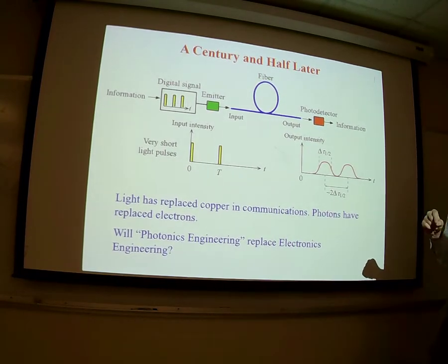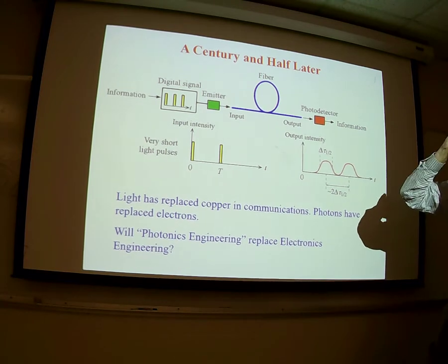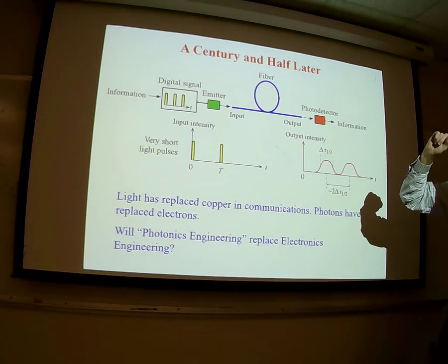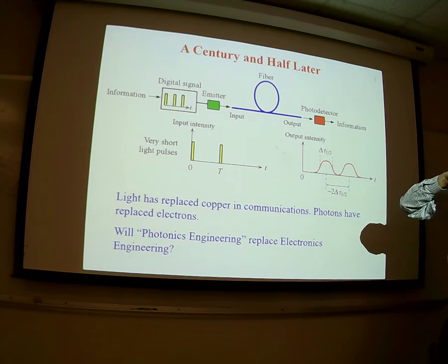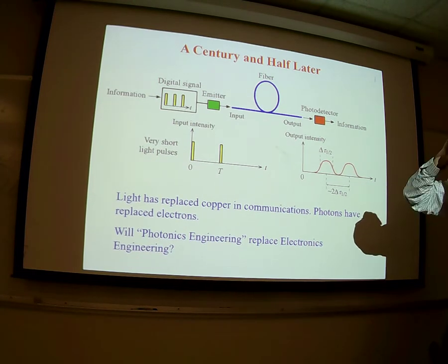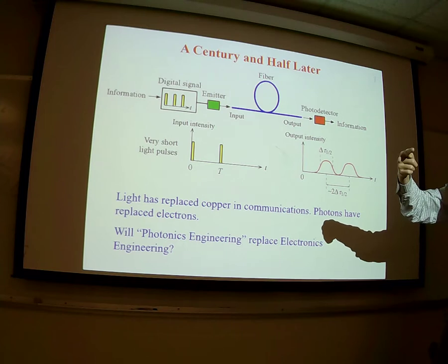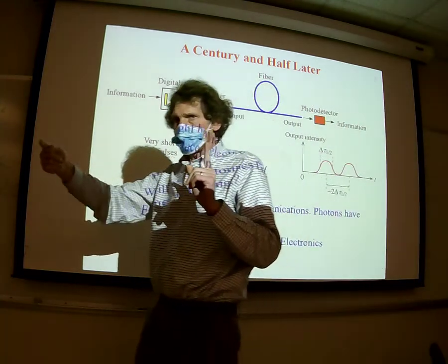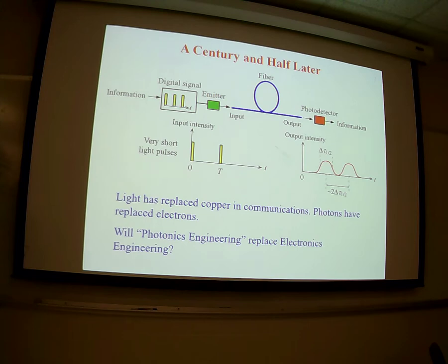Now, here's something. When you have these frequencies coming down a fiber optic guide, theoretically they would only have one velocity, but the reality is there's some dispersion. Do you remember what a wave with dispersion is? If you sent out a pristine signal in a packet, as it goes, it actually broadens out. It spreads because the velocity distribution will cause different frequencies to propagate at slightly different velocities. And the first thing you should ask is, well, I thought just one frequency propagates.